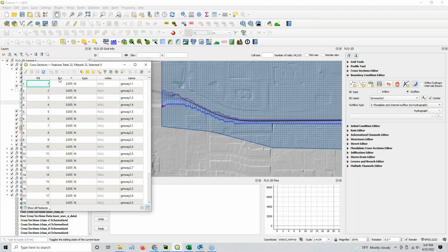So we set this. If you want to do that, you can see that there's no change in N value. They're all set to a uniform N value. If you wanted to give it something a little bit different, like maybe bump it up down here where it goes natural, or maybe make it a little bit lower up here, more something composite between a rectangular, or I mean a Gabion rough banks and the concrete bottom, then that would be appropriate if you wanted to do something like that.